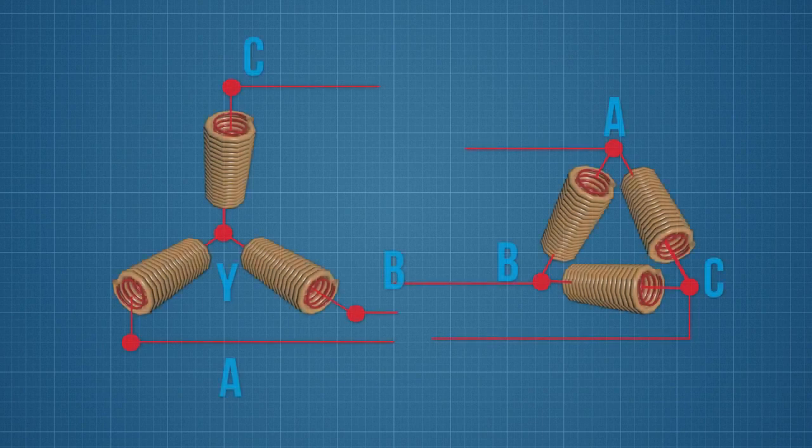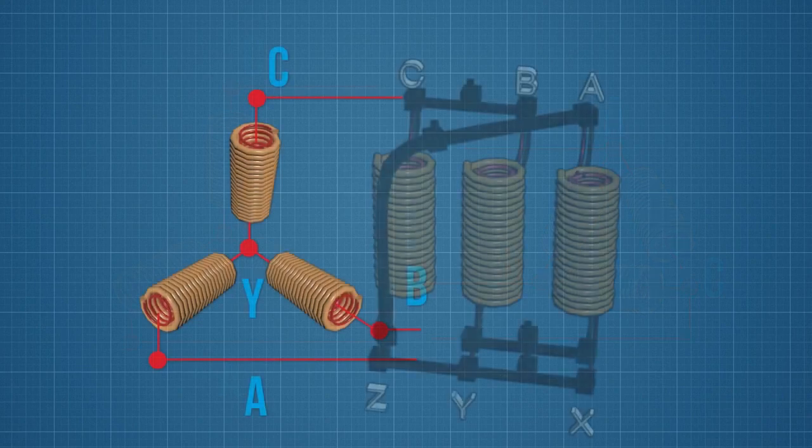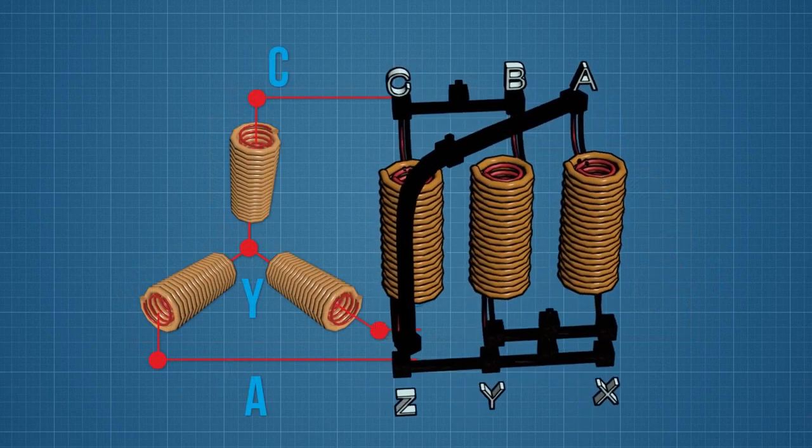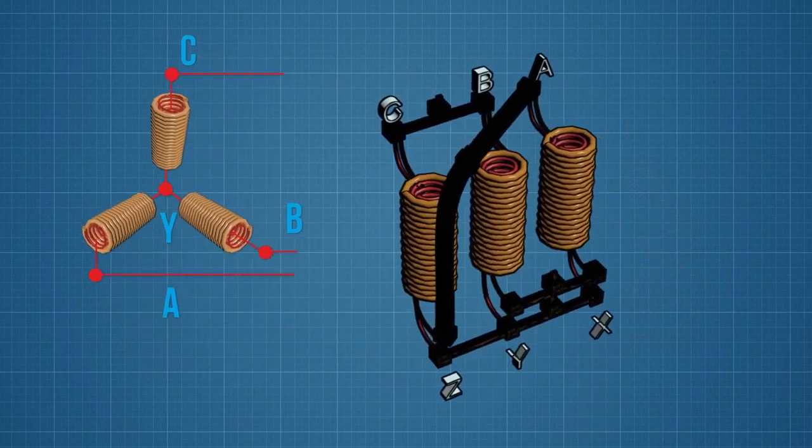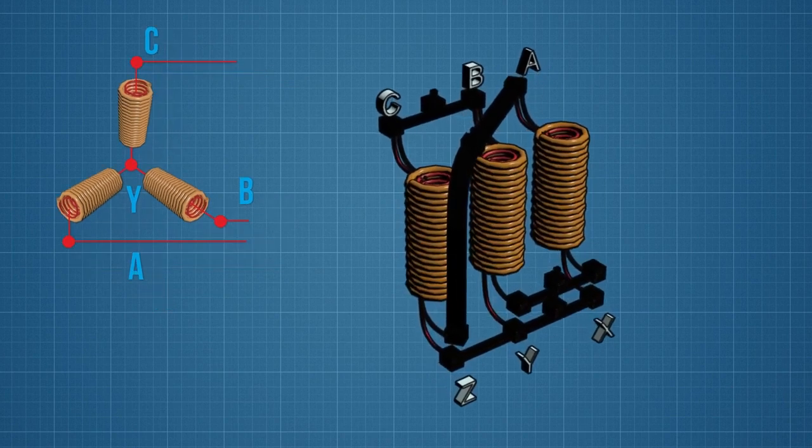Transformer windings connection diagrams. Various diagrams can be used to connect the windings of three-phase transformers. However, the power systems do not require many connection diagrams for practical purposes. Therefore, Y and delta connection diagrams are mainly used in both step-up and step-down power transformers. In order to obtain a Y connection, the ends or starts of the windings of three phases should be connected together.